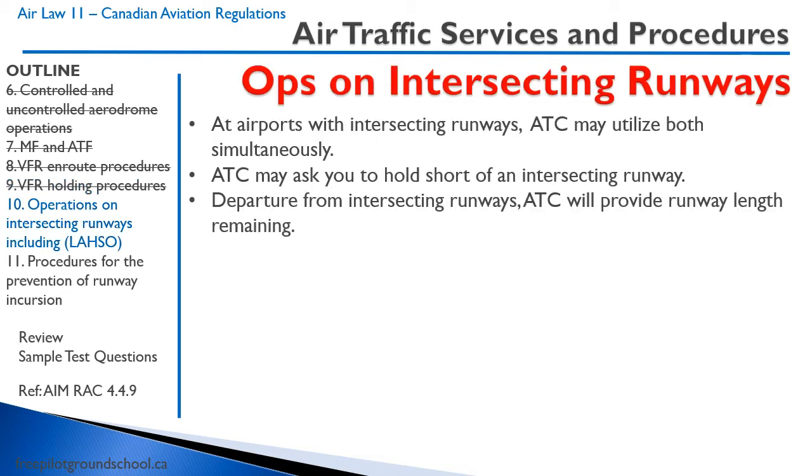At large, busy airports, there may be intersecting runways, and air traffic control will be utilizing both of them. Realistically, you won't be doing this too often as a private pilot because most airports that are big enough will have parallel runways, or they'll just slow things down. An example, though, of an airport that uses a lot of intersecting runways is LaGuardia. Often what they will ask you to do is land and hold short of an intersecting runway. They do this so that they can have another aircraft take off on that intersecting runway. You must, in that case, land and hold short of that runway. So think of it as simply a shorter runway.